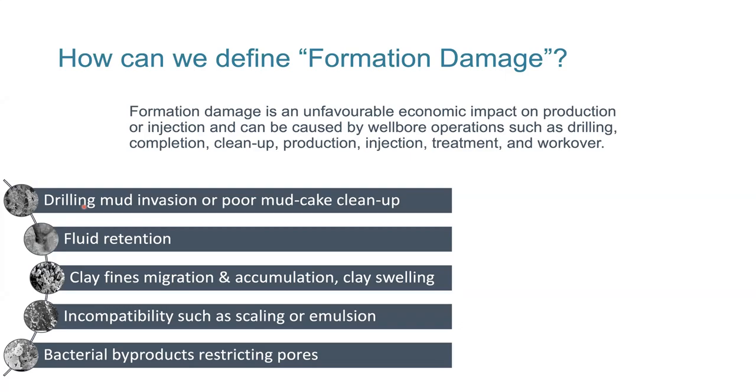Fluid retention is drilling or completion fluids going into the reservoir and then not being removed from the reservoir for chemical reasons, for compatibility reasons, for viscosity reasons, because we can't flow at a high enough rate or differential pressure through the near-wellbore. Fines. Now, in clastic reservoirs, everyone thinks of clay fines and they think it's a problem.